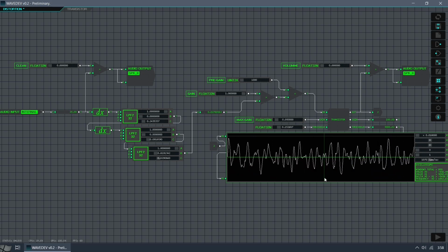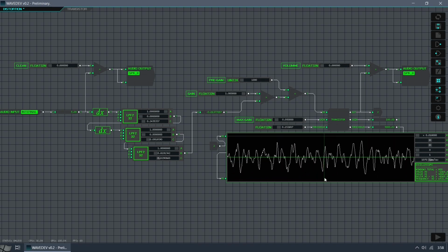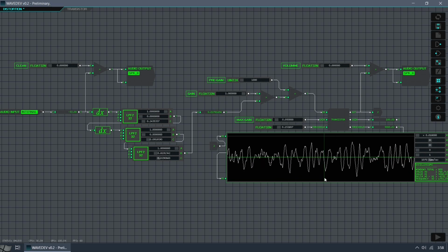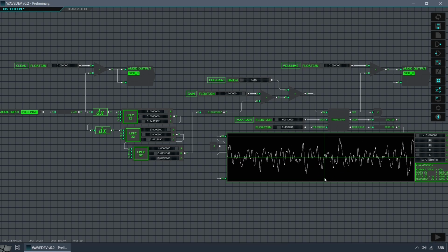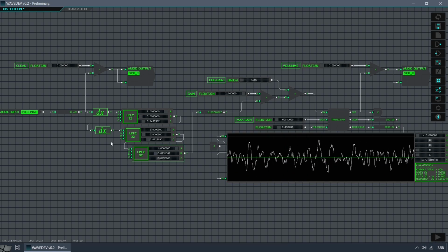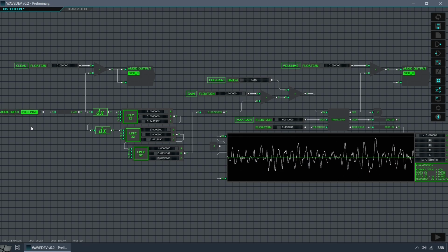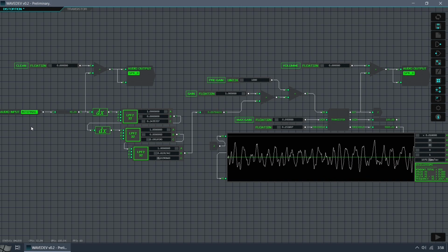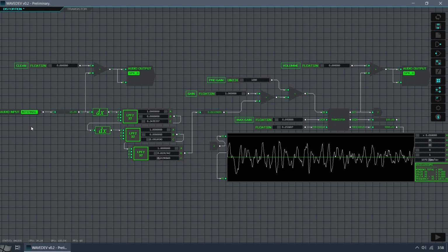So I'm going to fix this from the analog side. This deviates from the main programming topic since the hardware is now involved. But I have to talk about this a bit as it is just as important as the algorithm itself. The root of the noise issue is in the analog to digital conversion. I tried hard to fix a noisy signal in the digital world. But a poor conversion will lead to poor results no matter how many filters you apply to a sample.